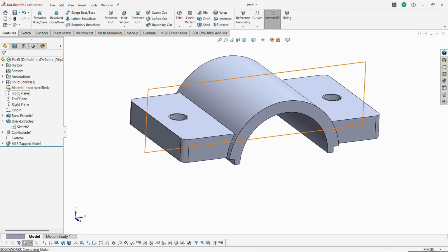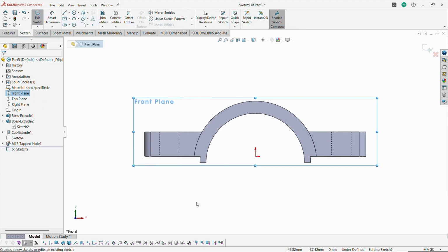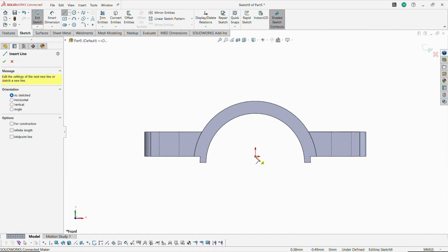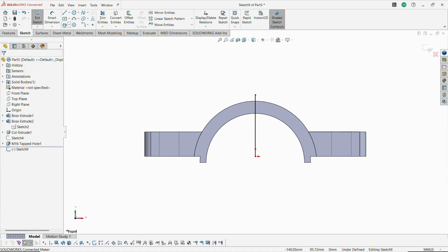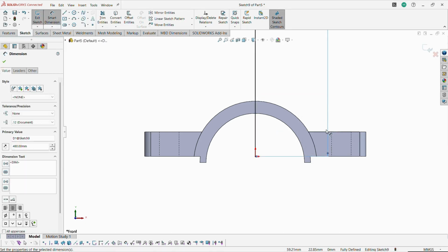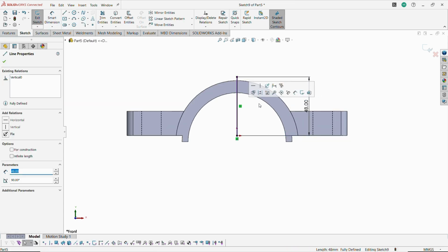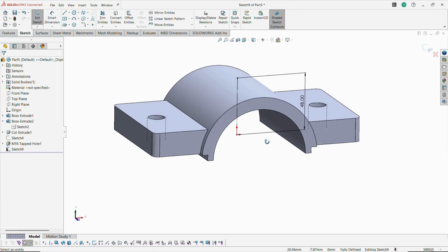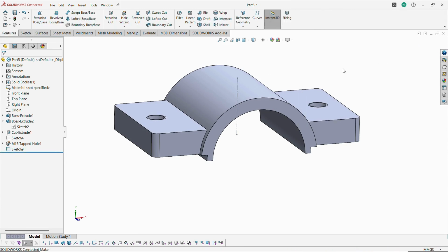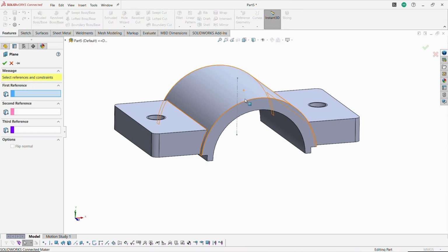Exit the sketch and form a solid body from the offset distance of 5 mm because the circle is not in the center of its portions right now. Now draw a vertical line, then initiate a distance of 48 mm. So mention 48 mm in this current category. Choose this and change it into a construction line. Exit the sketch. Let's create a plane.